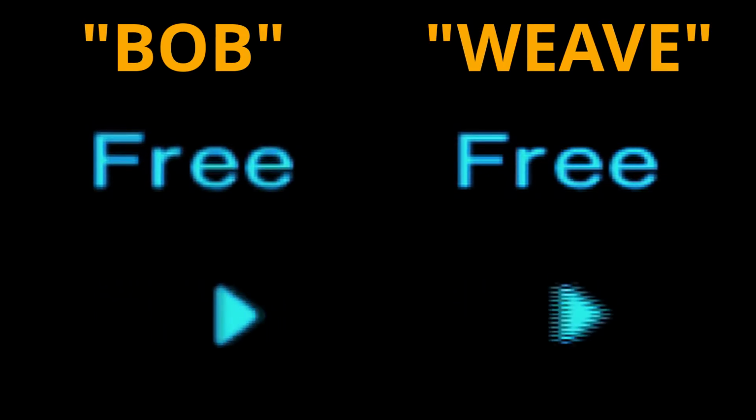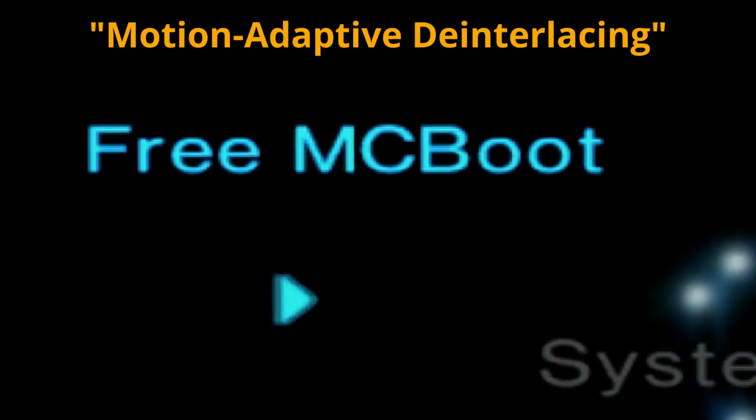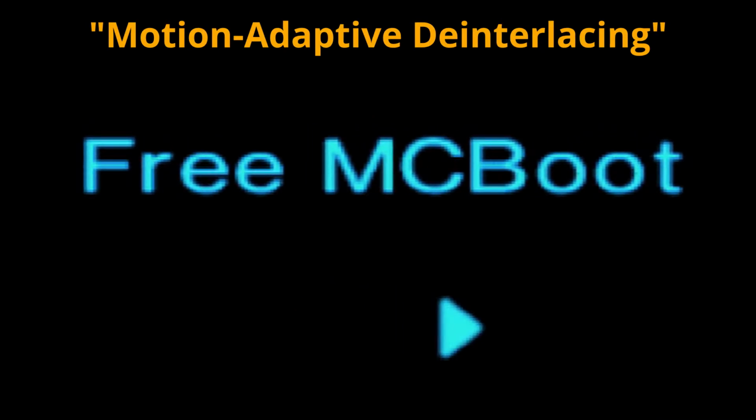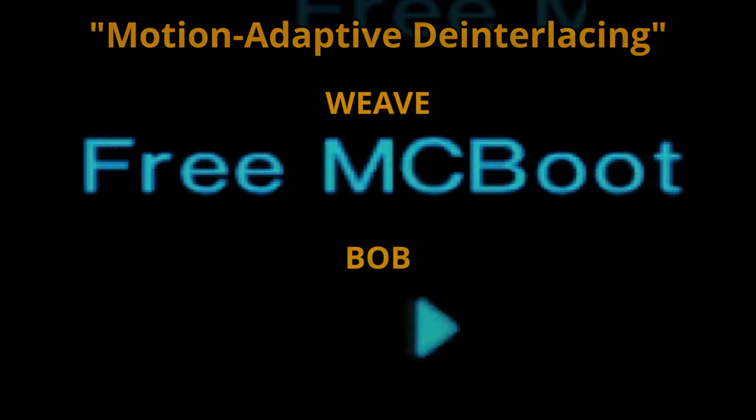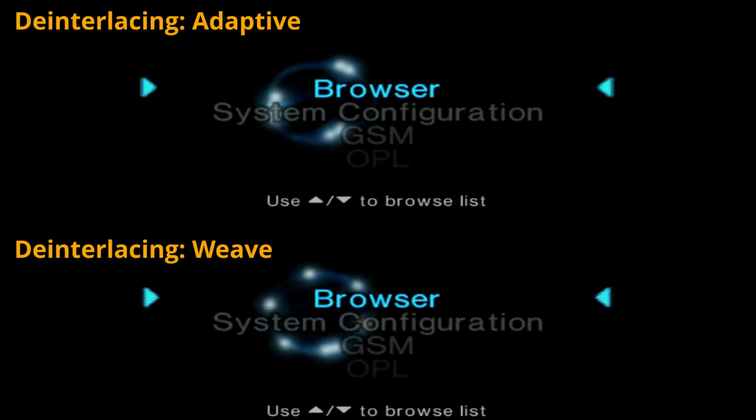representing static objects. The solution to this problem is to implement motion adaptive deinterlacing, where the current field plus 3 previous fields are utilized to detect the areas of the screen that are moving. In those areas, bobbing will be used, while the static portions of the frame are deinterlaced with weaving, resulting in a vastly better image quality compared to any of the two techniques used alone.